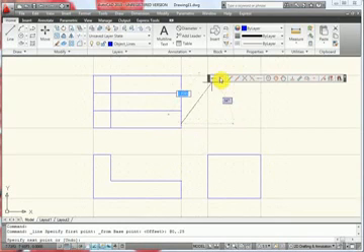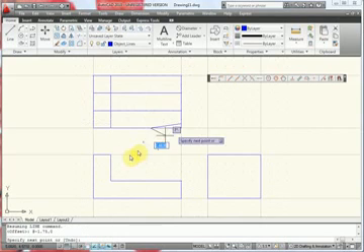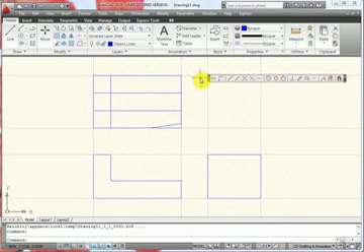Now I'm going to do that again by pressing the Snap From button. I'm going to pick the corner I want to snap from. And again, these are relative coordinates, so it's a coordinate based off that corner, that lower right-hand corner of the top view. I'm going to enter at -1.75, 0. Press enter, and now I have my line snapped there. I'm going to press the spacebar to exit the command. I'm going to press the spacebar one more time to re-enter the command.